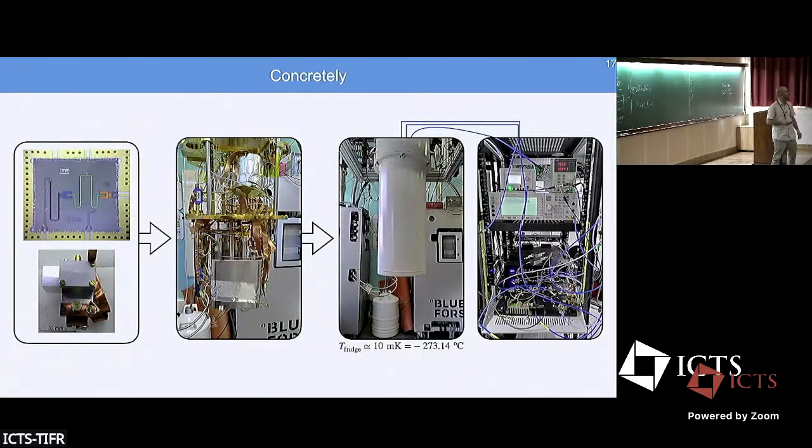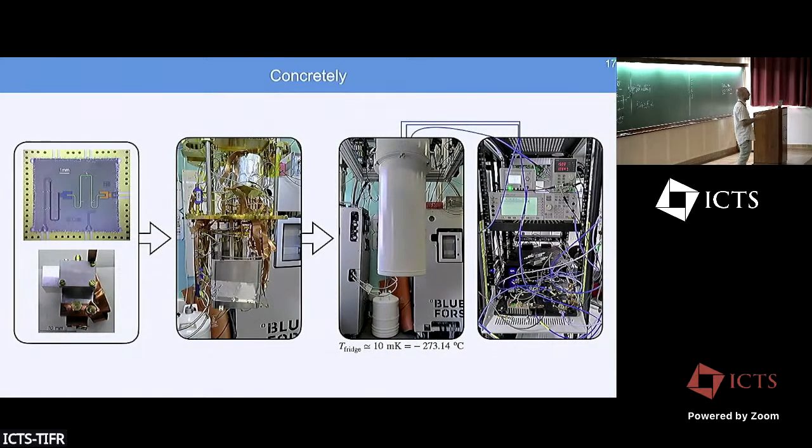Yes, so it really depends on the experiment. 3D cavities have historically got much better quality factors than 2D. So for longer lifetimes, it's better to use a 3D. Now for flexibility in tuning the couplings between systems and the design, it's much more efficient to do it in 2D. So it depends on what you want in the experiment.